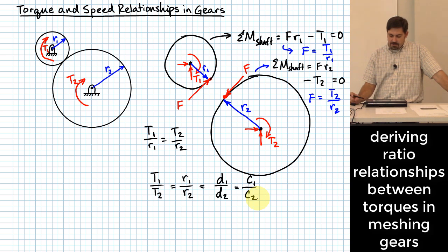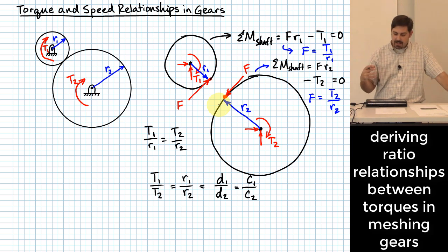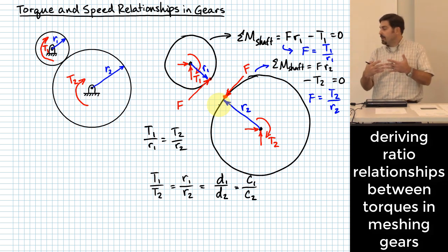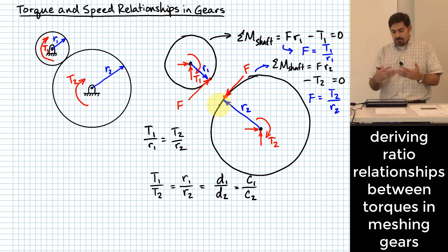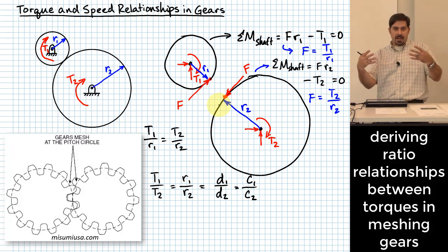Now we're going to go even another step. I've shown these gears right here as being smooth rollers, but they are only shown that way just to give you the basic idea of how they interface with each other. And with real gears, they do actually have these things called pitch circles, and they behave as if the two gears are rolling with friction on those pitch circles.